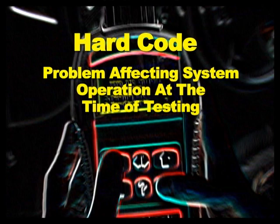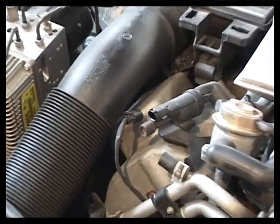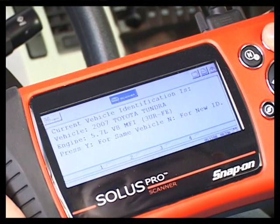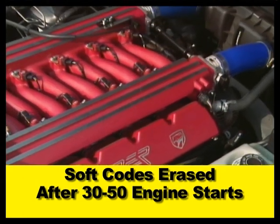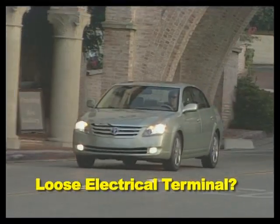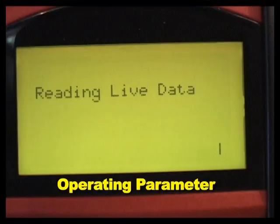A hard code or hard failure is a problem that is affecting system operation at the time of testing. An example would be a completely disconnected wire. A soft code or soft failure may not be present now, but is stored in computer memory. It might be present 1 minute and gone the next. Soft failures will usually be stored in memory for 30 to 50 engine starts. An example would be a loose terminal that connects and disconnects over bumps in the road.